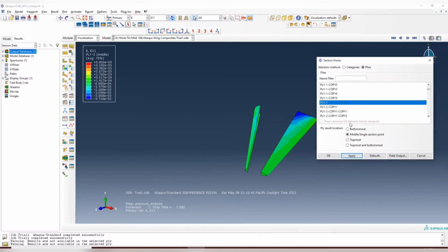Ply 2. This is a little bit, I think it's still okay, but what about ply 3? So this is a good guess. That means you can see the compressional stress for the first 5 plies is all smaller than the desirable value. Then let's see what about the tensional stress. So let's see the last 5 plies here.